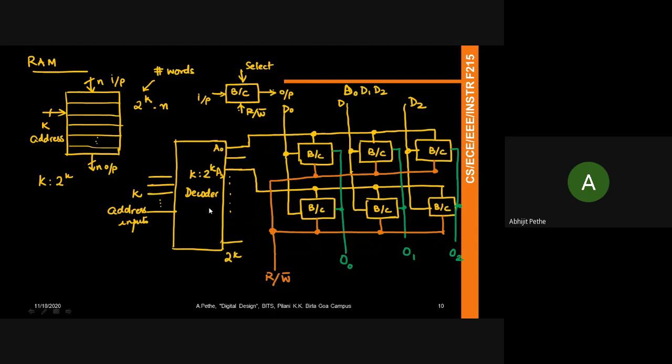When you start doing circuit level design, we did a very simple decoder using static gates in this class, but we'll see that there are a lot of interesting designs you can make with transistors for a decoder, and all of them basically trade off speed for power.